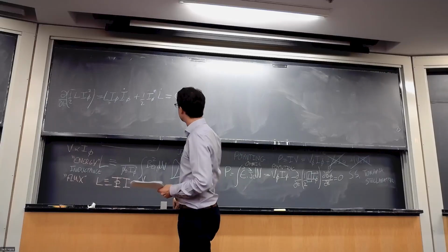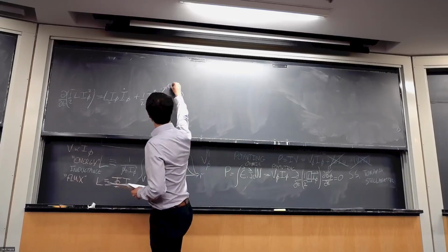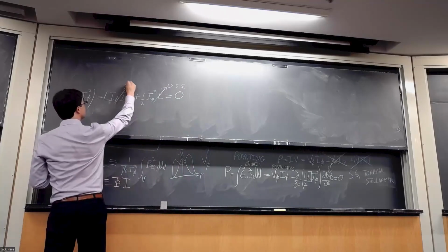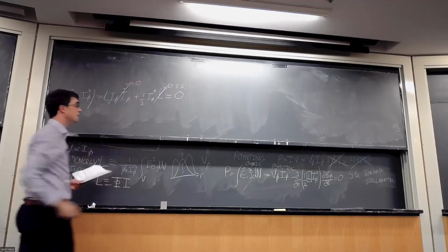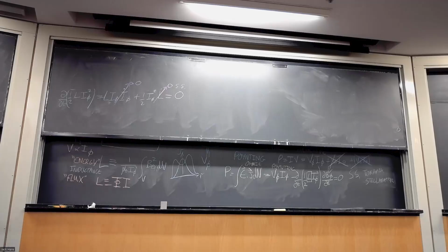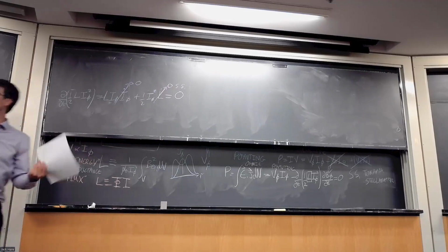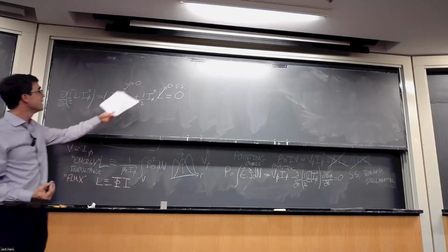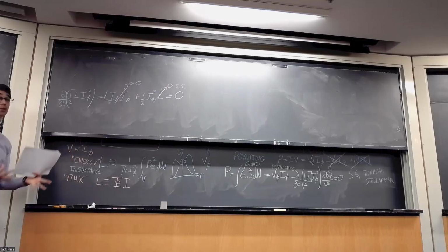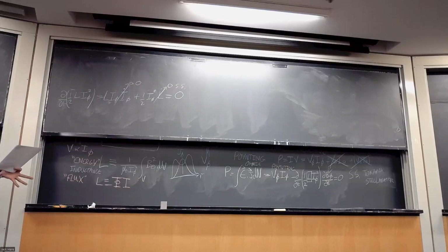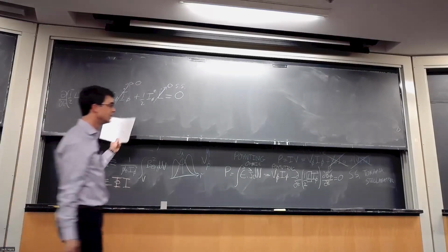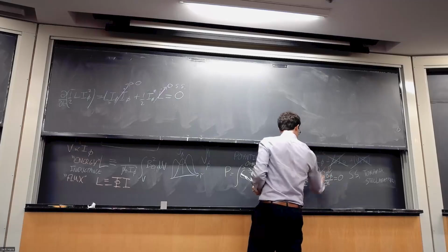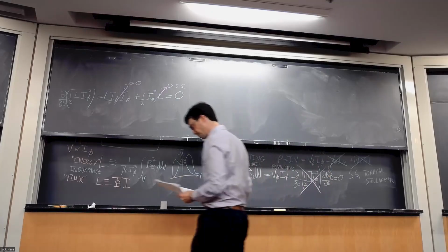I'm going to set it equal to 0 because we're saying that this is 0 because we're in steady state. And slightly weaker, we're going to just say that this is roughly 0 compared to the other things. The reason we're doing that is we can't set it to exactly 0, otherwise we wouldn't be able to sense it with our Rogowski, and we would have completely failed in this task. But we're going to say that it's small enough that our Rogowski, which is super sensitive, can get it, but it's not big enough to actually cause a change to our overall picture here. So we're going to be able to get rid of this term entirely. Okay.